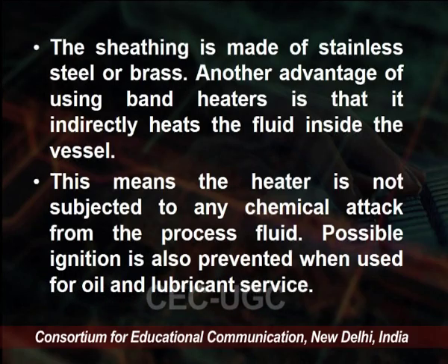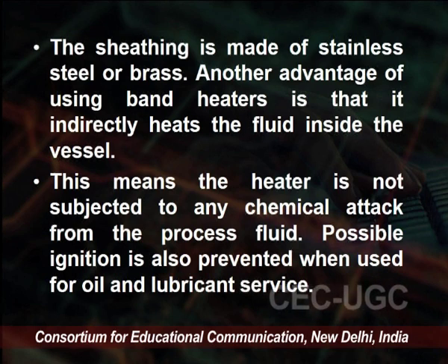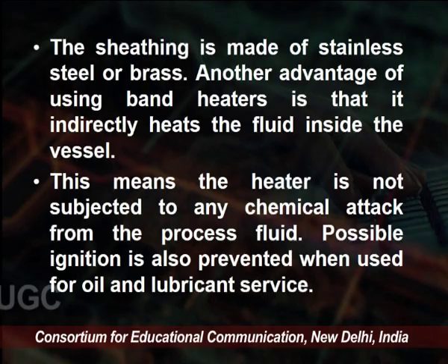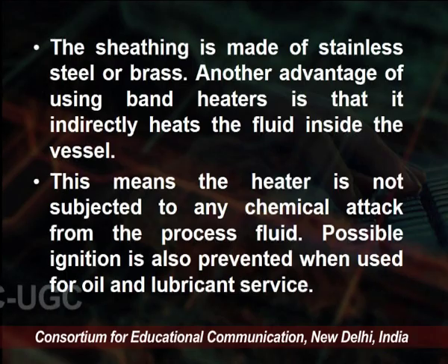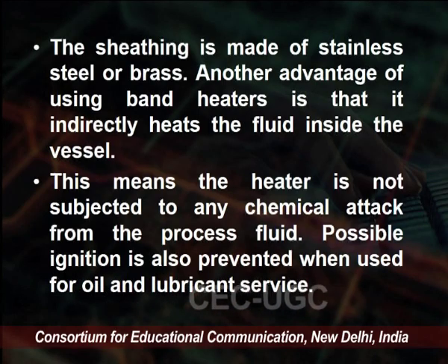Another advantage of using the band heater is that it indirectly heats the fluid inside the vessel. This means the heater is not subjected to any chemical attack from the processed fluid. So, possible ignition is also prevented when used for oil and lubricant services.